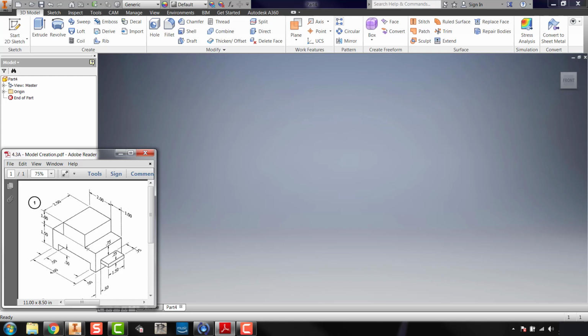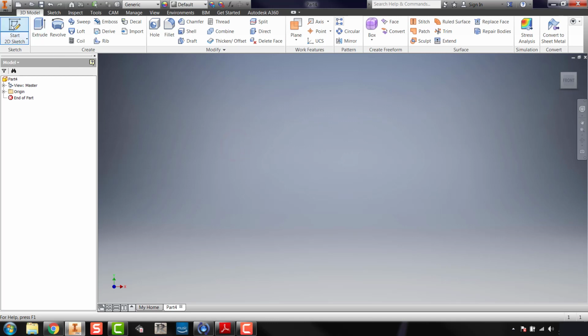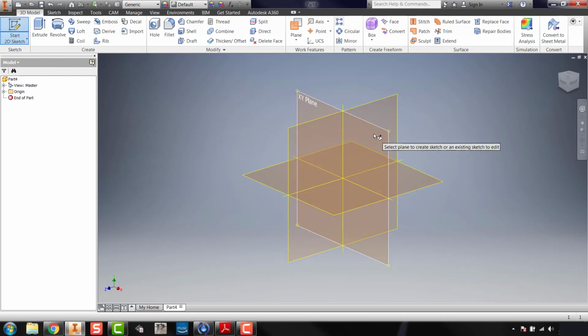And for me, I'm going to initially use the subtractive method to create the overall shape of this block. So I'm going to go into Inventor, and I see the overall width, not including this extrusion on the right hand side, of this body here is 4 inches. Its height is 2.5, 1.5 plus 1, and its depth is 2.5. So I'm going to create a new sketch on the XY plane.